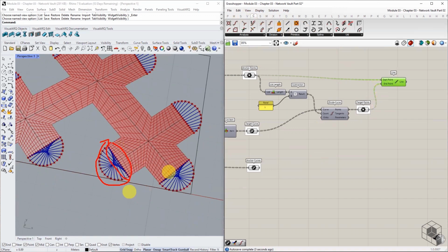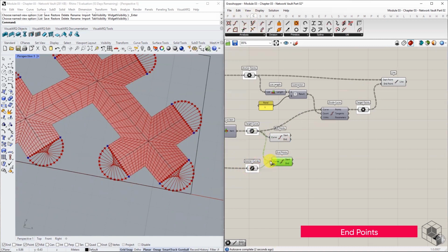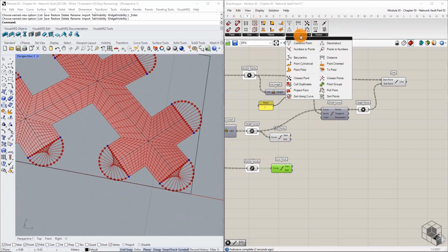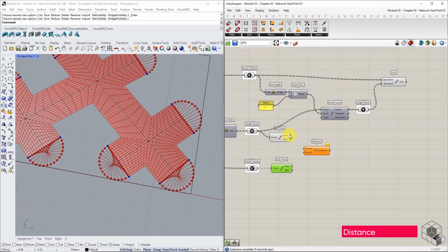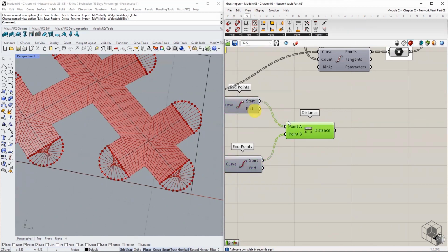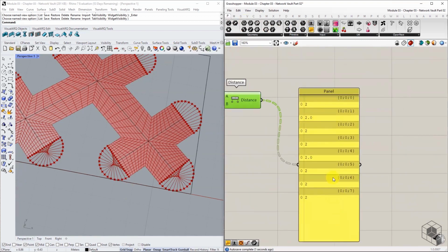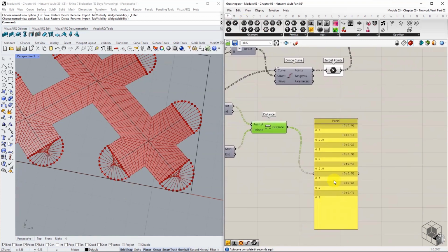To sort the anchor list, use the anchor curves as guide curves. Before doing that, ensure that these guide curves and the target curves are aligned in the same direction. Use the start point of both target and anchor curves, and check the distance between them. If the distance is non-zero, the curves are not aligned.